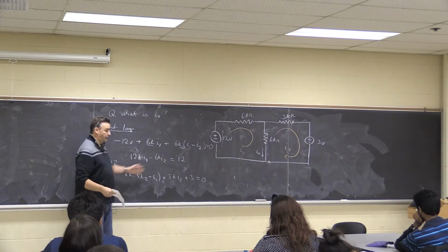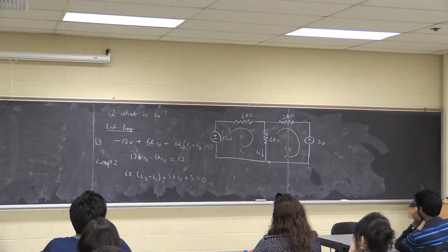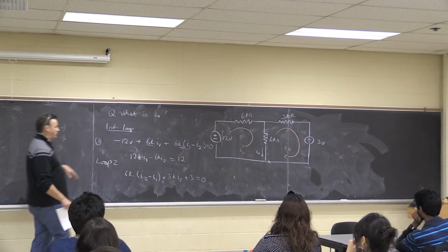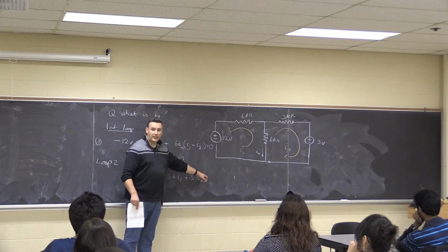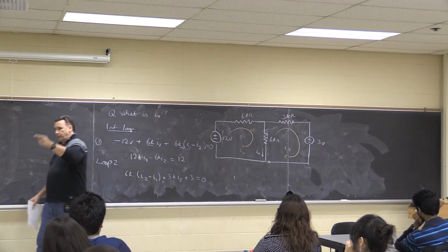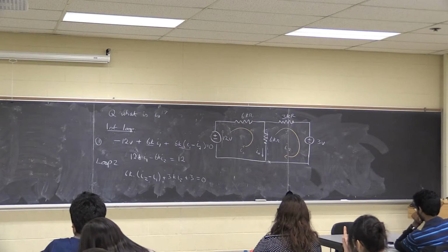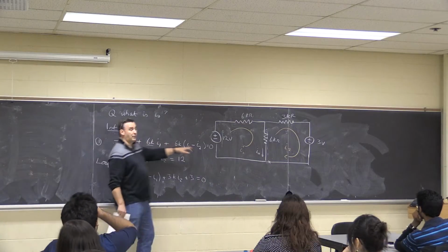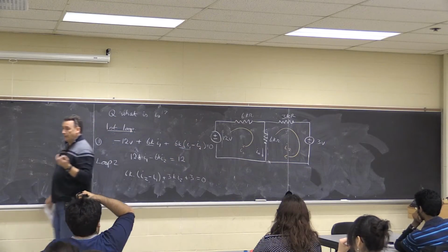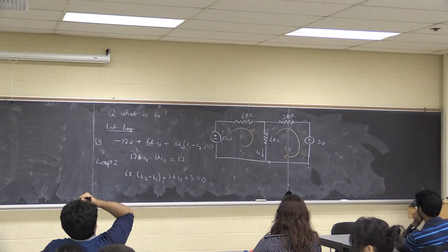And that's consistent with voltage increases and voltage decreases going around the loop. If I moved the voltage source to the other side of the equation, this would become negative 3, but the current is going into the positive terminal, out of the negative terminal of this battery. So it's going in the opposite direction from what I would normally expect. If I just had a battery and one resistor, the current would come out of the positive and go back round into the negative. So the loop current I've defined has to be flowing in the opposite sense.